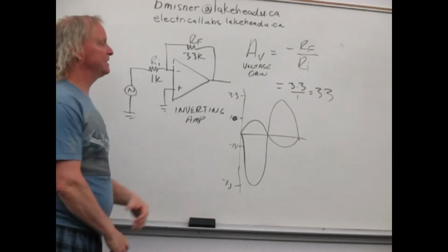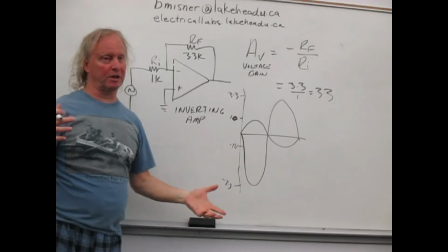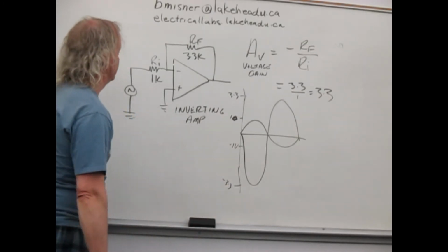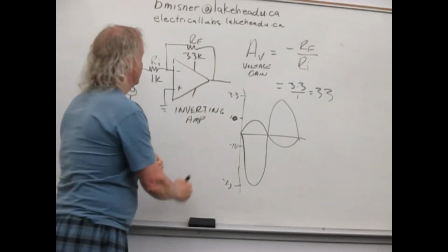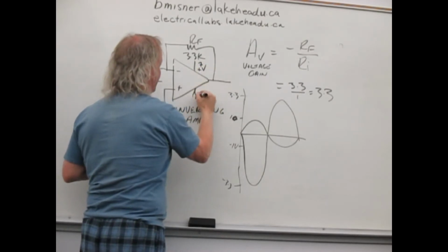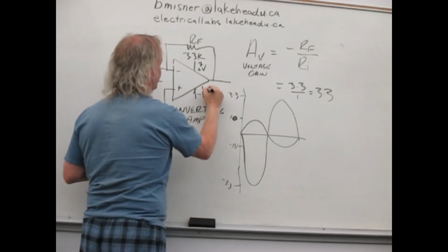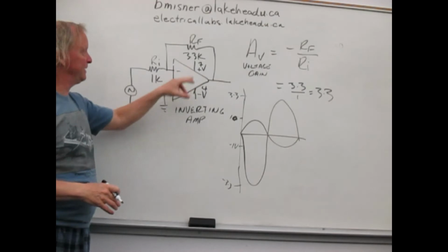One of the other things that I haven't showed you is that these amplifiers have power supplies. They run off of voltage. Actually, I erased the IC. This is going to be pin 7 for the plus voltage, and then this is going to be minus V down here. This is pin number 4. So on the IC, these would be the different connections.